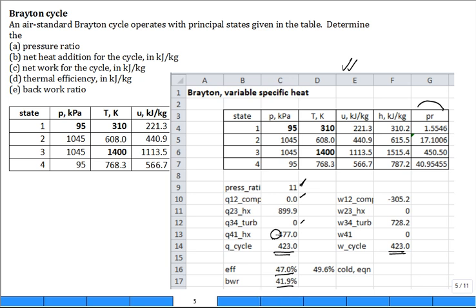The air tables are implemented in Excel, and so you can call that PR. I think the call in Excel is PR_T for temperature_air, and then you have to feed it the temperature in Kelvin, and you'll get the PR. That's built into the Excel tables that are available in the computer. This was not downloaded from the University of Alabama. That's not from them. It's what we generated here with student help before.